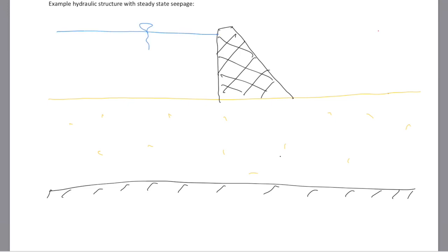Okay, so if we construct a dam just like this, what's going to happen is water is going to flow directly under this, and if it moves rather too quickly, it's going to start bringing the soil particles with it, and eventually more and more water will come out, and something that is called piping will happen, basically creating a conduit for water, and the hydraulic structure will fail.